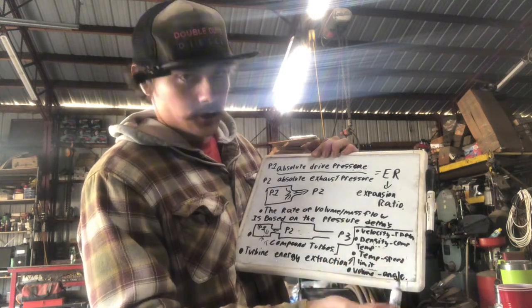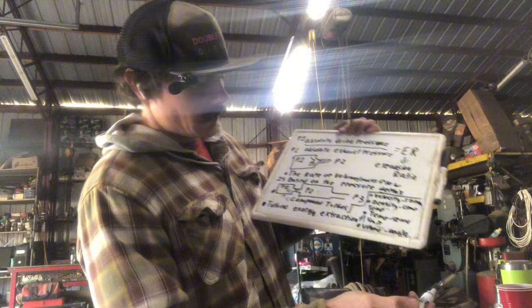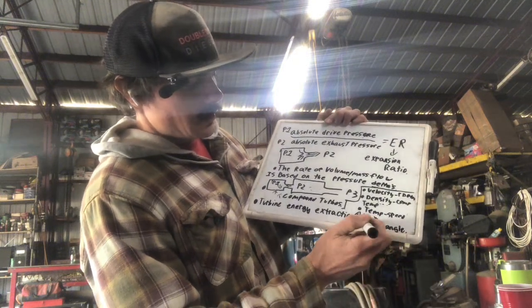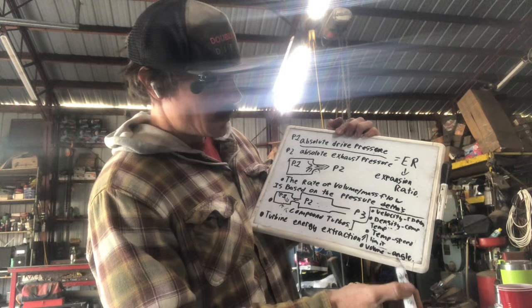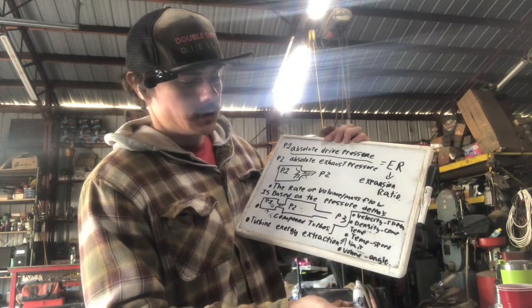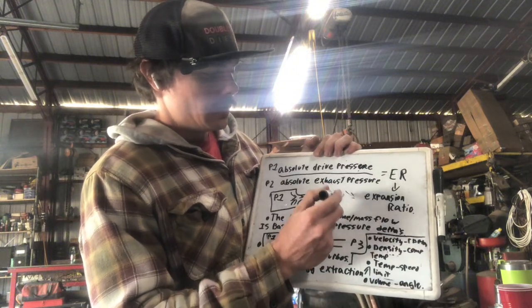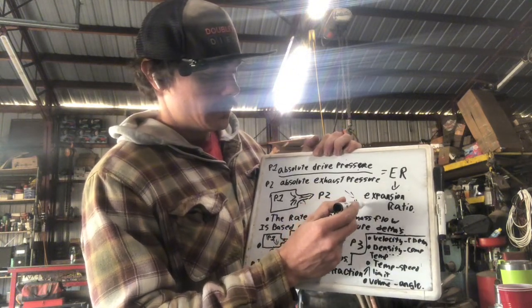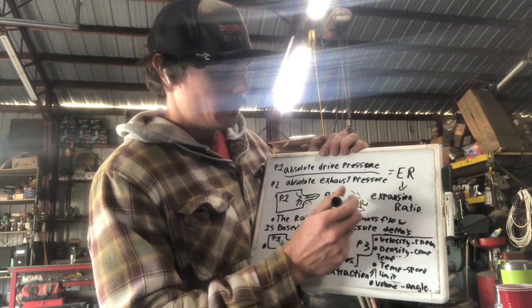The temperature sets up your speed of sound limitations, as well as the pressure. Sets up your speed limit, right? And ideally, you can't go any faster than that. Then volume is mainly a geometric constraint as far as the angle of attack of the exhaust gas into the turbine wheel. It's like a turbine blade, right?